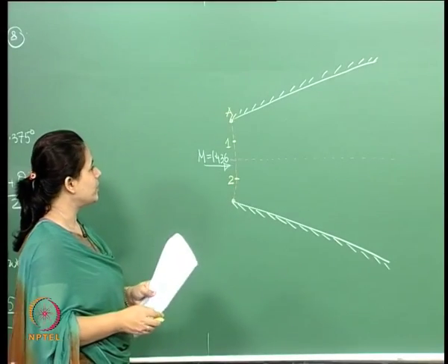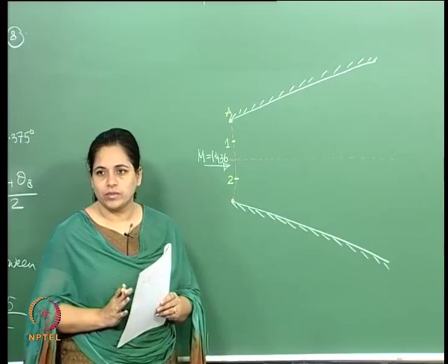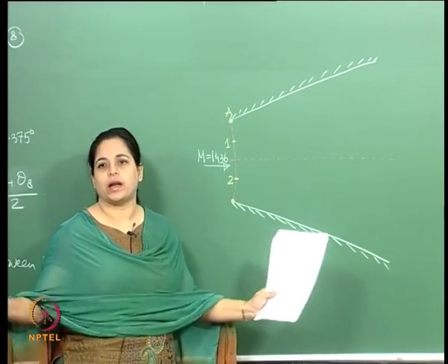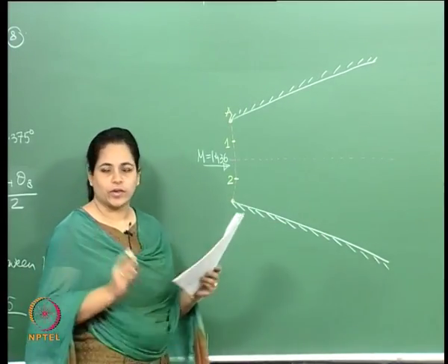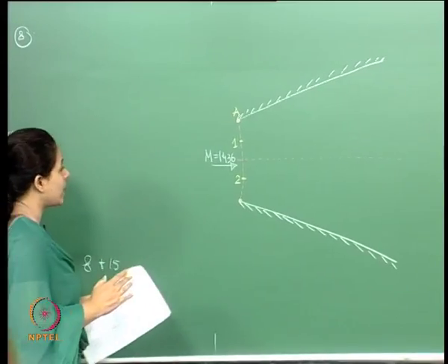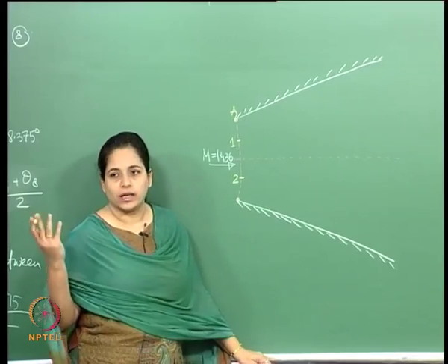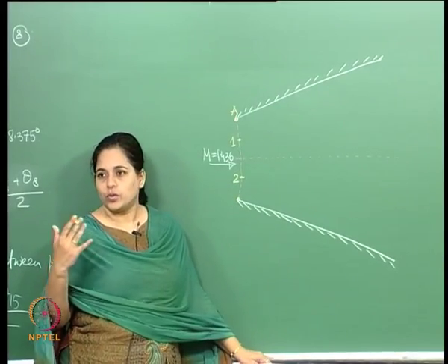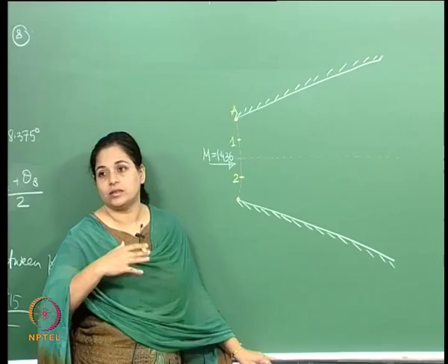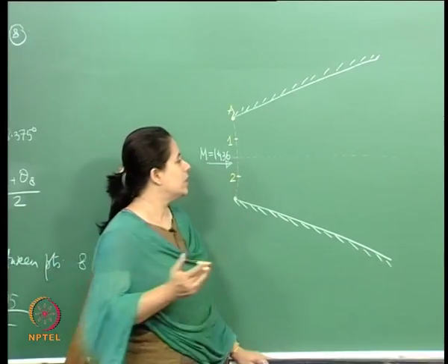Now what is happening? Basically the flow is expanding, isn't it? So it is an expansion fan. We will draw this expansion fan, and unlike the minimum length nozzle, now it can expand over a length. It is just a channel. So it is not necessarily a centered expansion fan.